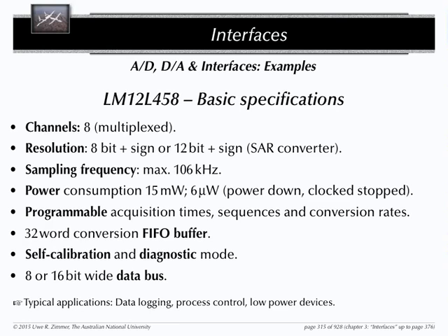Think about the previous picture, where we see 32-bit conversion in FIFO mode, a first in, first out buffer inside that chip. This only makes sense if you assume that this device works on its own. If you needed to trigger every single conversion actively from the CPU, start converting that one, give me the result, start converting this one, give me the result, I wouldn't need that buffer. But here you operate differently. You tell this device, start converting at this frequency from this input channel or those 5 input channels and dump all the results into this buffer, and let me know when you only have so and so many words left in the buffer.